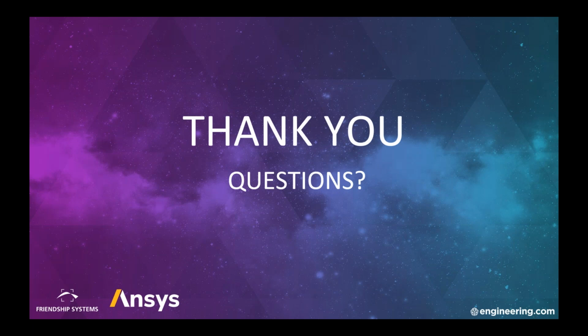But I know at least that people have done optimization, and that's something I'm aware of from the marine field, that optimizations are often run for model scale computations because of the high Reynolds number of the full scale, and then translation factors, so to say, can be taken into account for scaling the model scale results to full scale results.